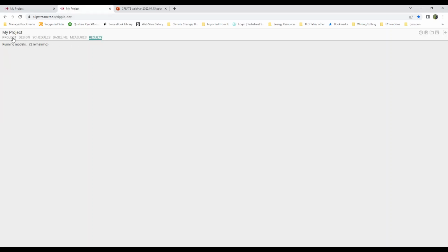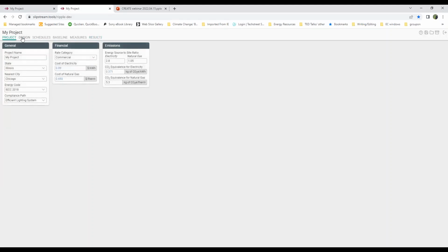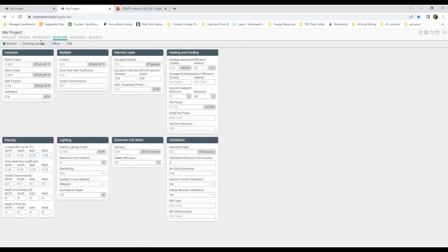So for a student that would be doing this as an exercise, walking around, I would say that the envelope inputs are kind of harder to look at, because once the wall has been constructed, unless there is an exposed wall somewhere, it's not really easy to see what type of insulation is inside the wall, how many inches of insulation there are, which makes it a little bit more complicated to calculate the U-values.